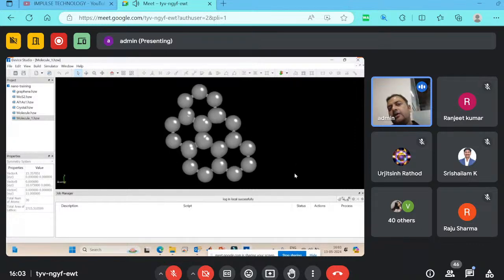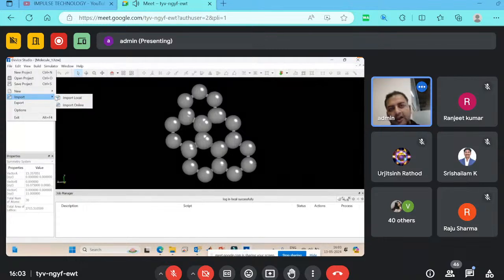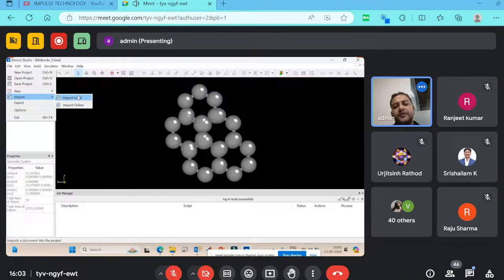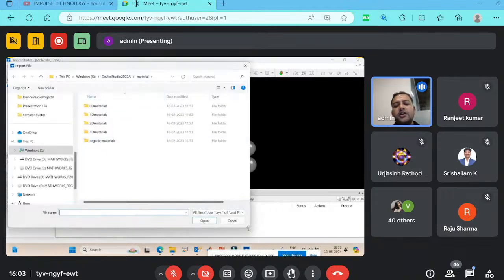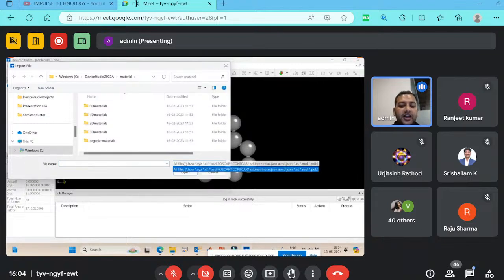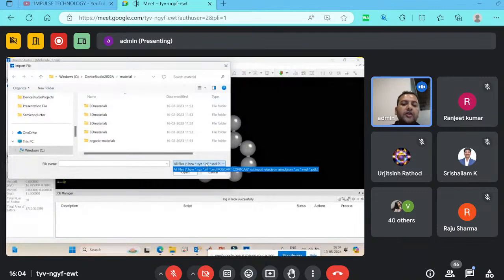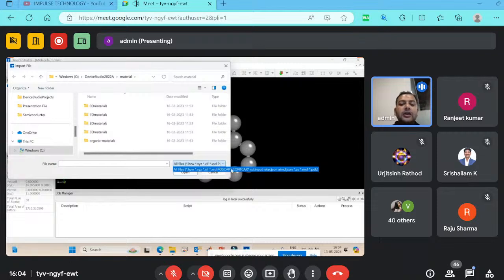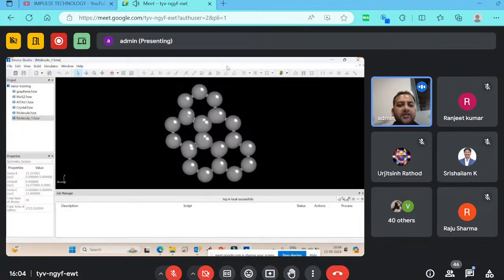So we have a crystal builder, molecular builder, device builder, and the import option from the local library and from the online library. Online it can fetch, and locally it can also fetch. The fourth option is called third-party database. If you already have an HZW file, XYZ extension, CIF file (crystallographic information file), XSD file, POSCAR file, CONTCAR file, FCF.import, or relax.json, you can upload it. So there are 4 options I have suggested to load your material in our dashboard.